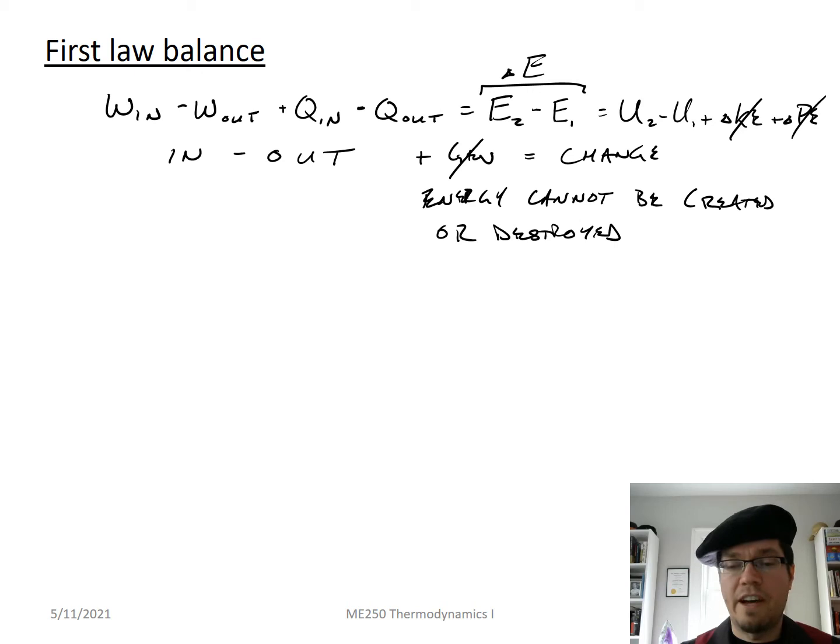We can further simplify this equation. Are we doing work on the system? Well, yes, that gas is being compressed by the piston being pushed by the spring. So there's a force acting over a distance, force of the spring acting over the displacement of the piston. So that's a work. The force and the displacement are both in the same direction, so it's a positive amount, and they are acting into the system. They're both directed into the gas that's inside that cylinder. So that is a work in, yep.